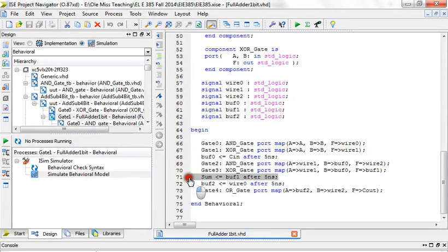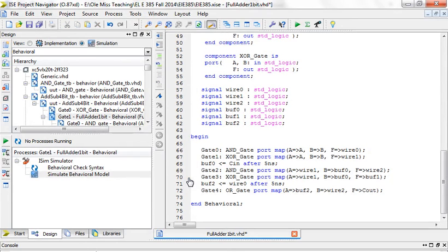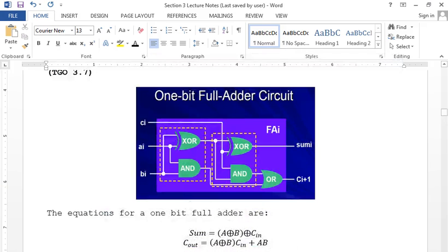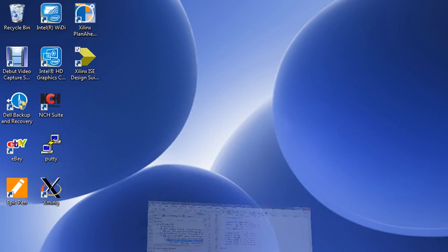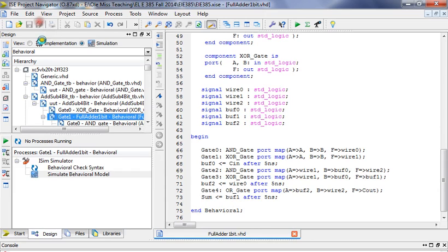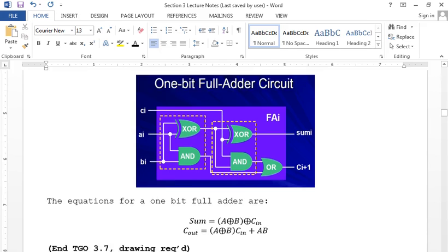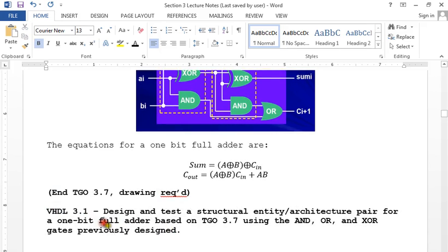So I'm going to change one thing really quick. It's going to be the exact same layout, but I wanted to make sense why I'm adding the buffers where I'm adding them. So now, after that, we have our last thing, which is our OR gate, right? So we have 5 nanosecond delay calculated into the OR gate. And so now I'm buffering the sum bit by 5 nanoseconds, right? And that is what we did here. I'll be expecting you guys to do what I just did.